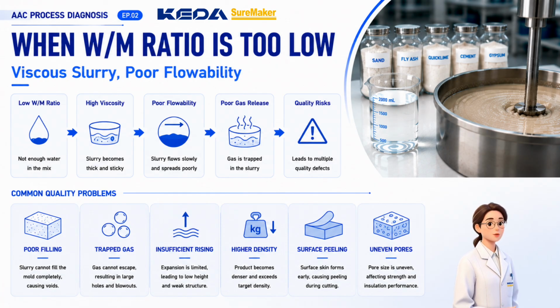The gas expansion height may be insufficient. Gas may become trapped inside the green cake. Large pores may remain in the green cake matrix, mainly because the air is not fully released by vibration. The final product density may become higher. The product surface may peel, and the pore structure may become uneven.